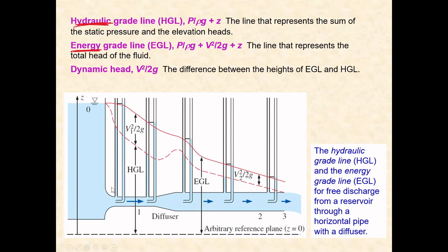You can see that in different parts of the pipe we have a piezometer as well as a pitot tube. Both the piezometer and pitot tube combine to form the measurement unit for velocity, because here is a point where stagnation happens.